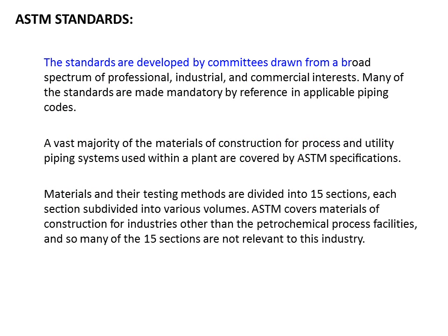The standards are developed by committees drawn from a broad spectrum of professional, industry, and commercial interests. Many of the standards are made mandatory by reference in applicable piping codes. A vast majority of the materials of construction for process and utility piping systems used within a plant are covered by ASTM specifications.